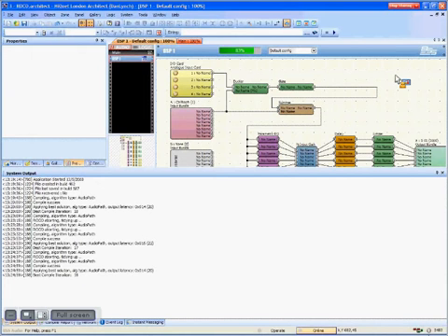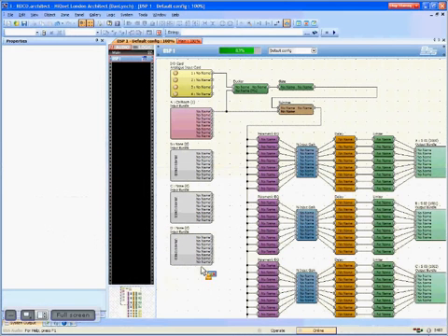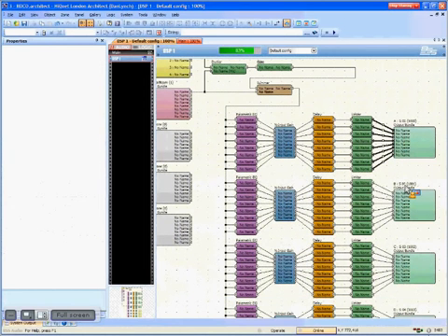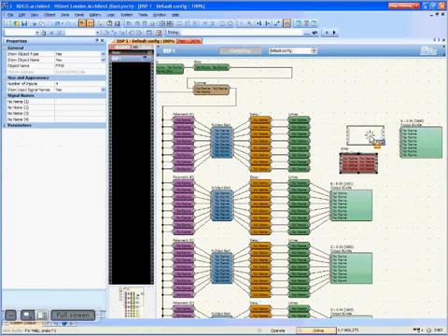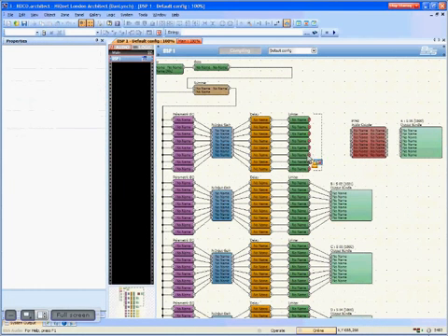The first one I want to talk about is the audio coupler. And you guys actually saw the audio coupler earlier in the room combined example file I showed you. But I'm just going to take these wires out, slide this over, and give you a little real world example of what the audio coupler is for. Under Tools, Audio Coupler. It starts off 4-channel, but you can make it up to 32. For this, we just need 8.